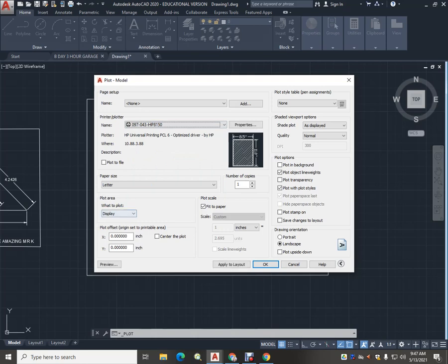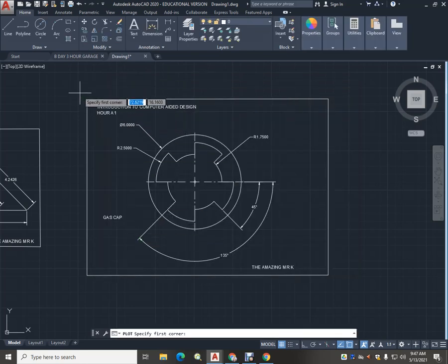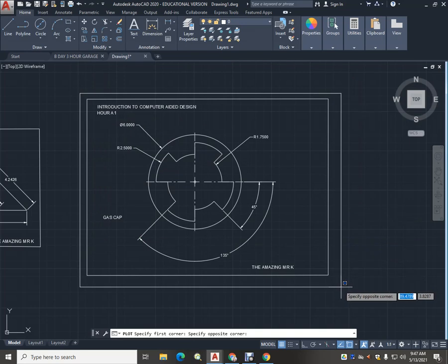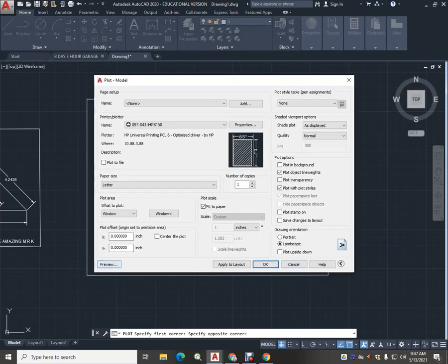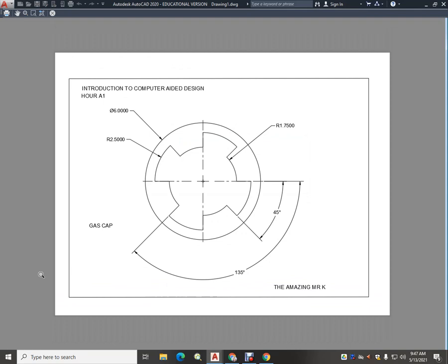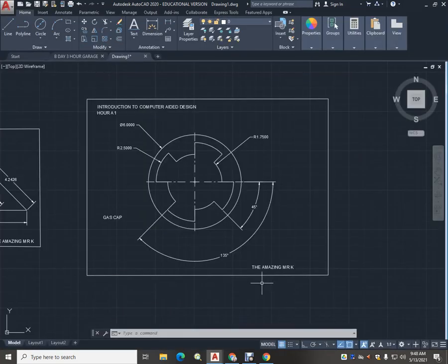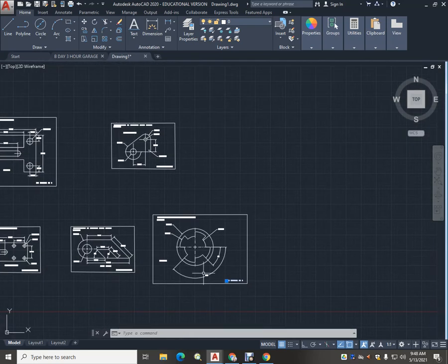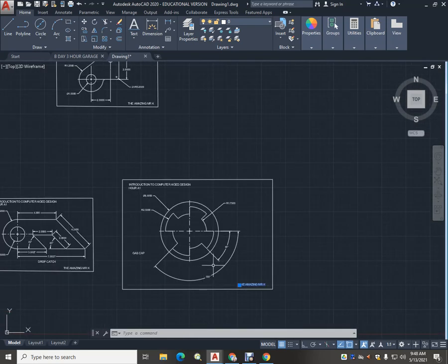And that's what AutoCAD is trying to do right now with your made-up title block. It's trying to force it into an 8.5 by 11 piece of paper. And see, there you have it. If I was really a stickler, I might try to pull the top line up just a little bit. But I think that gets the bell for us. Nice looking drawing. So you would want to print that, put it under the light, collect 2 cookies, and you'd be on your way.